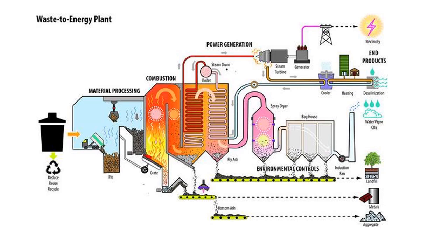So this is what a diagram of it looks like. We can have our municipal waste, and with that municipal waste we can do the 3 R's: reduce the use of things and eliminate trash, or at least reduce the use of trash, reuse many things, recycle many things. But what can't be, or what they decide should instead go to an incineration plant, will be sent there. It will typically be dried, shredded, combusted, and inside the combustion chamber or the furnace, you're going to have the pipes that have the water, which is going to turn to steam, and that steam is going to power a turbine, which powers a generator, which generates electricity.